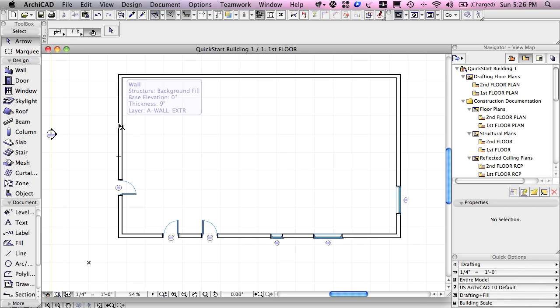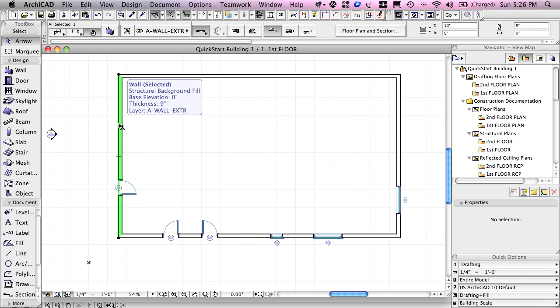I'll go back and again click on this wall, and this time I'll go up to this other wall on top and position my mouse there. And you can see that again it has the pre-selection color blue. It shows that there's a wall, the little floating information that's translucent, and when I want to select it, I click. And you see now it's changed. So by clicking, I've selected this one, but I've had ArchiCAD just ignore or forget the other one.